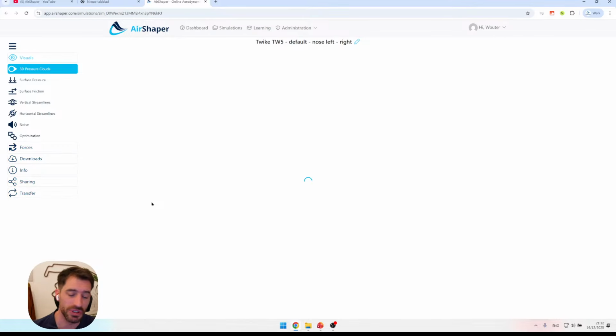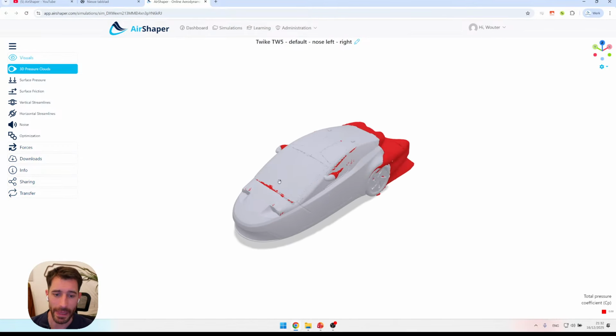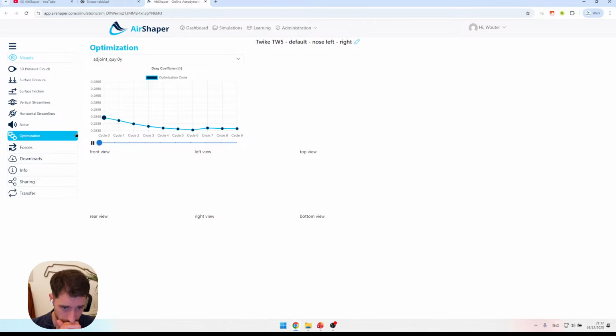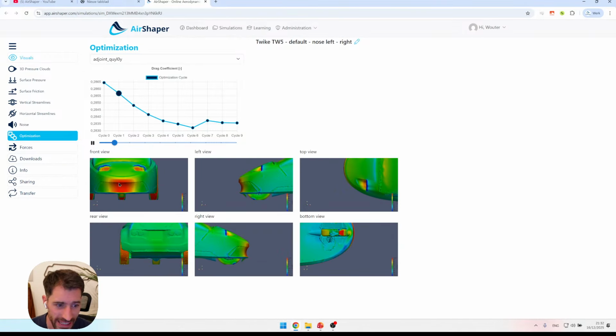And then this one was also instrumental in optimizing the car. We wanted to optimize the splitter left and right of the front wheel, and surprisingly, the software was telling us, well, please pull up the front splitter. And that's, for many people, quite counterintuitive, because you would think if you push more air underneath the car, you would actually just increase the drag, right? Well, in this case, it was the exact opposite.